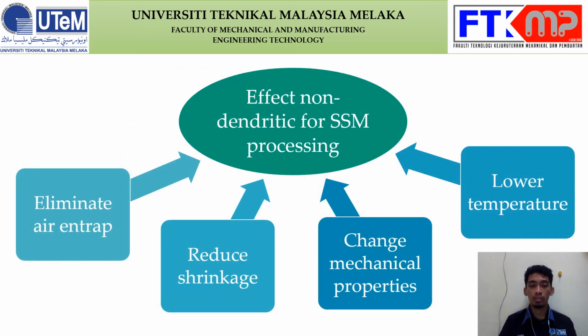Effect of non-dendritic structure for semi-solid metal processing. The SSM is processed at a lower temperature. This can eliminate air entrapment and reduce shrinkage. The mechanical properties of the grain microstructure change depending on the technique or method applied.